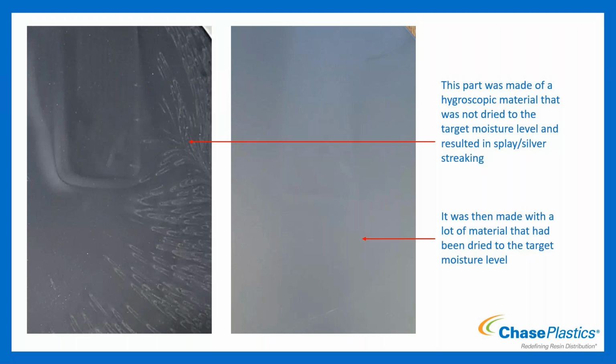So if you have a part that has a requirement to perform a certain way, if we degrade it, not only will it look bad, but it's also not going to perform well. So with our polymers, if we need to dry it, we need to dry it. We want to make sure that we're drying it appropriately. We run into a lot of issues where drying is not done, and then you end up with subpar parts and material appearance.